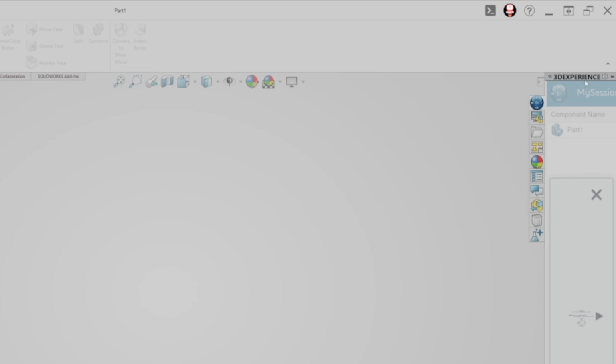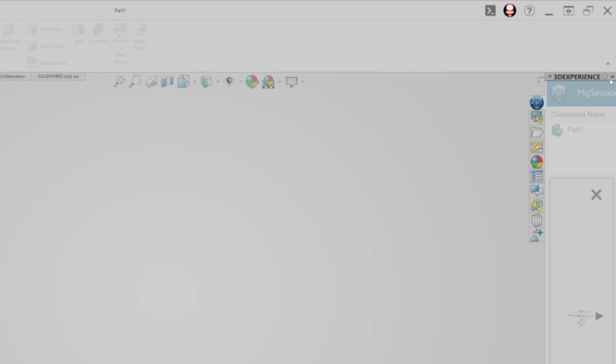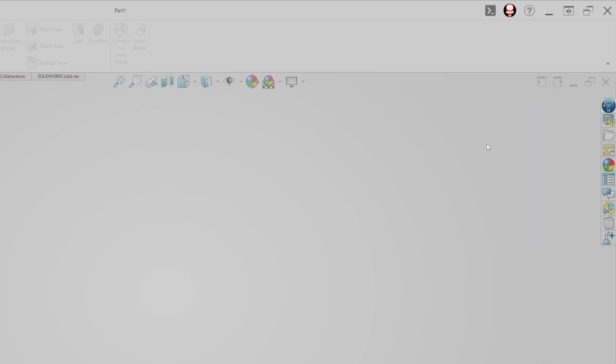So you may have this panel pinned open. It should work as a flyout. If you click in the gray space behind it, it should pop out. And then we do not need to worry about this panel on the right-hand side any longer. If you click in the gray area and it does not hide, then the panel is pinned. To fix that, go up to this thumbtack icon. Click the thumbtack until the pin is horizontal, then click in the gray area and the panel hides.